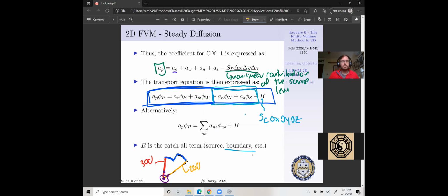What you have to do is just ignore that node. So for axisymmetric problems, that's tough. In this pie slice problem, you lose information down at that corner of the pie. But with this, we can actually cover that because we're not evaluating our equations at our vertices, we're evaluating at our cell center. So this makes the incorporation of boundary conditions a little more robust.